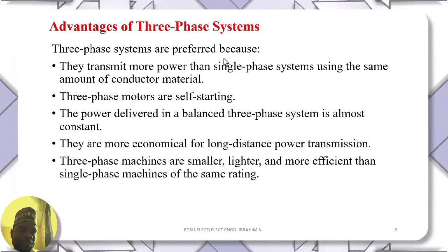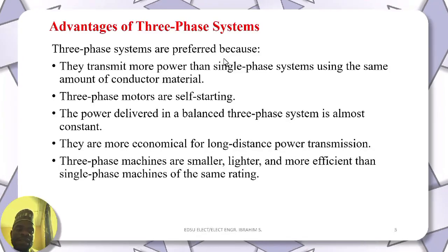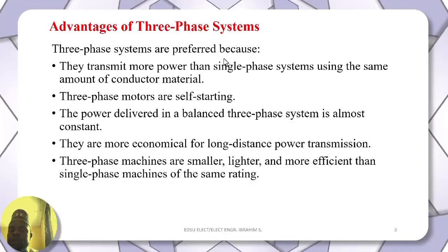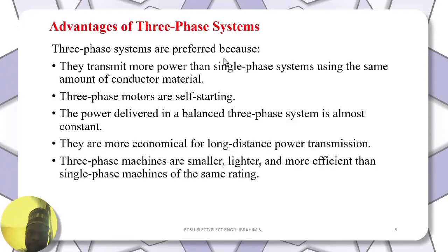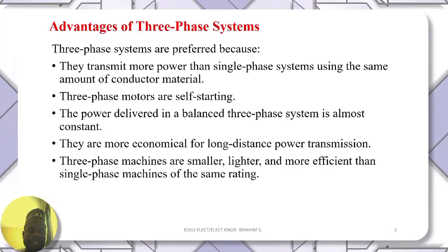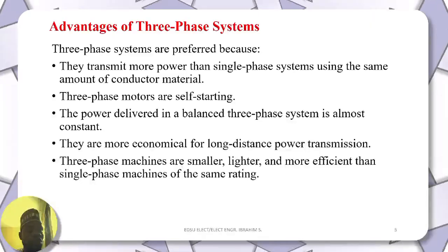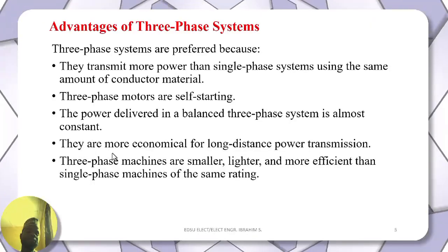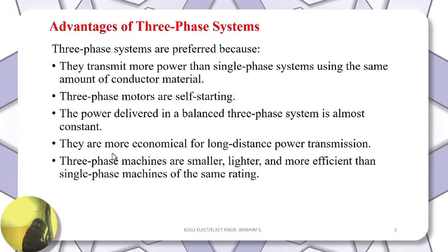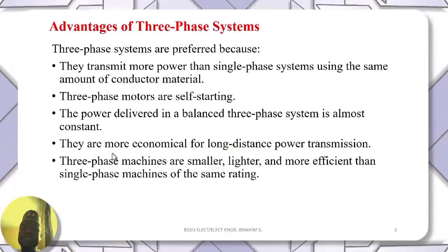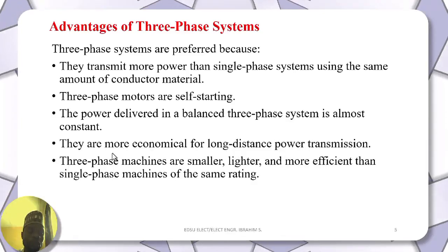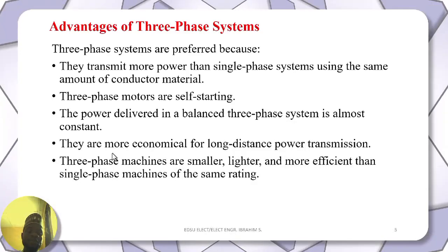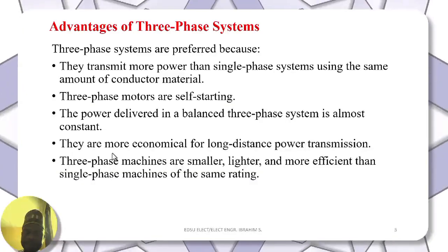Then two, three-phase motors are self-starting, and three, the power delivered by a balanced three-phase system is almost constant. Then the next is they are more economical for long distance power transmission. That is why we tend to use three-phase for power transmission. And also, three-phase machines are smaller, lighter, and more efficient than single-phase machines of the same rating.